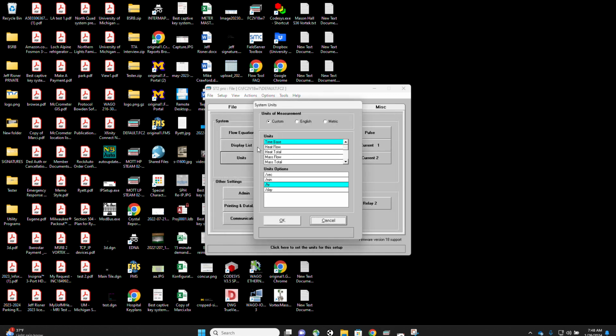All right. The units for our time base, heat flow, we want KBTUs. That's 1,000 BTUs. Heat total is KBTU. Mass flow is pounds per hour. Mass total is pounds. Volume flow is going to be, well, I have to go back and change our time base to minutes.